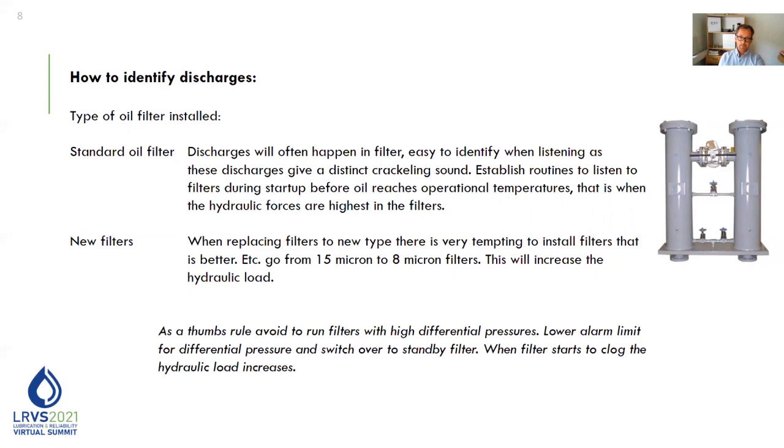We also have clients that have run into problems just by doing what is the right thing, installing better filter elements. But then, of course, you increase the hydraulic load. Also, we tell our clients that they should pay more attention to the differential pressure over their filters. We even suggest lowering the alarm limit, and being quick to switch over to the standby filter, so you keep the hydraulic load as low as possible during operation.